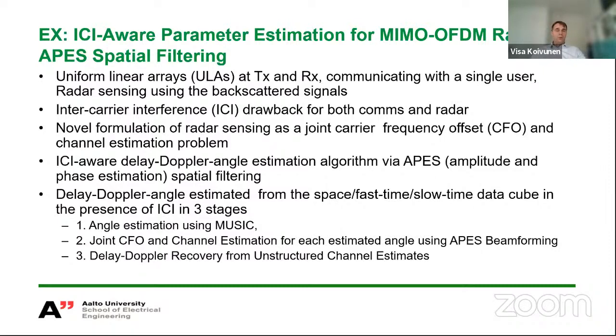You figure out these angles using the MUSIC algorithm, and then you do joint carrier frequency offset and channel estimation using this APES beamformer, and then finally delay-Doppler recovery from unstructured channel estimates. And the idea here is that, even if these targets would have the same angle or the same range but different Dopplers, or the same, anyway, even if two of these three are the same, then you could still resolve these targets and so on,